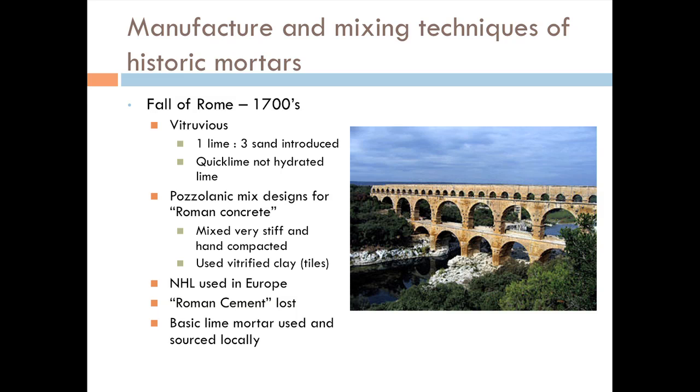So then we start getting into the 1700s. Vitrified. Oh, that word. Okay, that would be where a material is heated up to a certain temperature. So with your firing clay, or something like ash from a volcano, it reaches a glassy form. And it's a good thing you mentioned that, because these silicas need to be amorphous or reactive, and it only happens once these materials reach a certain temperature. Roughly, some type of melt phase could be anywhere from 1800 degrees Fahrenheit and above. You start seeing this chemistry come about.